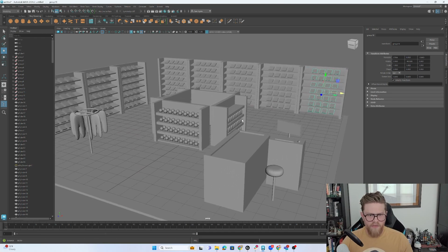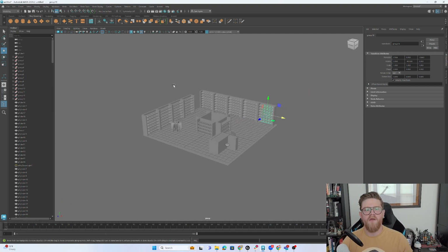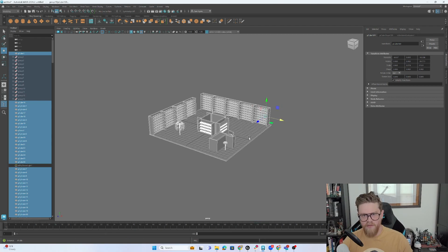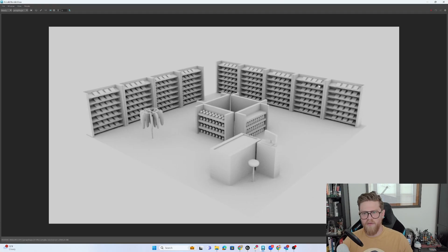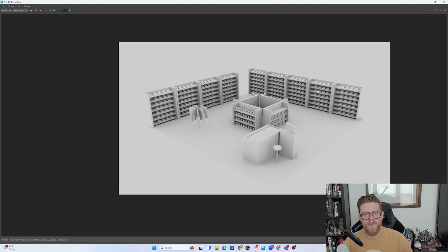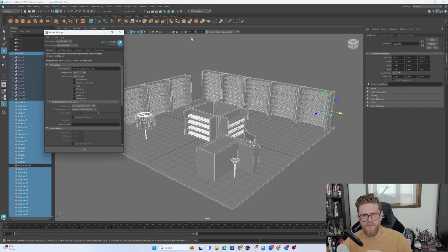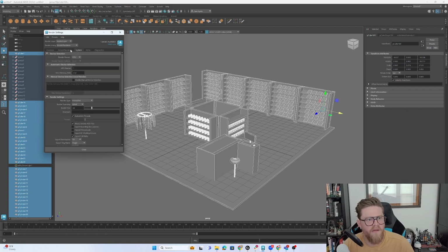Now let's pull us back over to our render. Again, we don't care about what's facing away from us. Let's make sure we have everything in here. Hold down that right click, assign the existing ambient occlusion Arnold material, and then come right back up here and do the Arnold render view. That is not too bad. So now I would start to play around with the actual render quality and settings. If I come into here, I can change some of the diffuse, specular, the AA, etc.